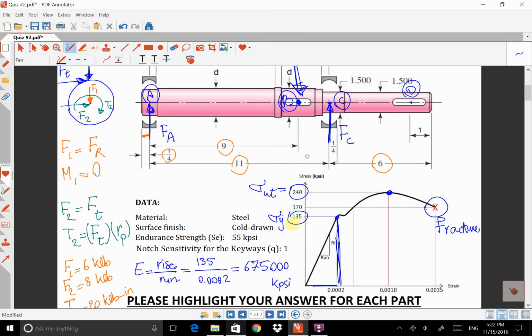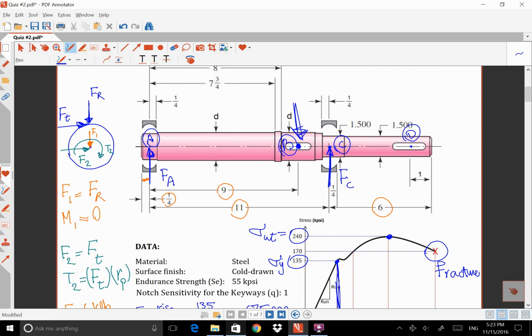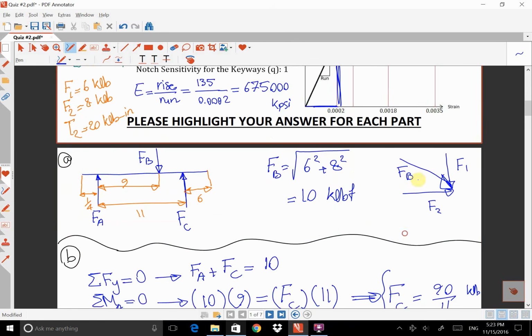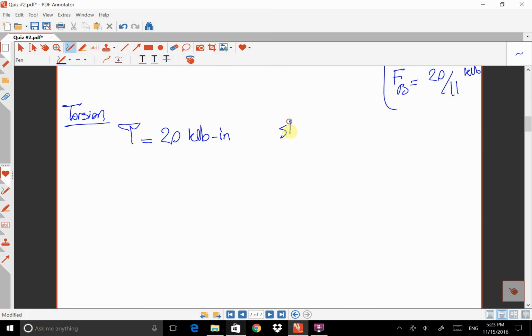If I come to the question, usually torsion comes to a system at one keyway and goes out from the other one. So in this question, that torque applies at point B, and it's going to go out of the system at point D. So we don't have any torsion before point B and after point D. So I'm going to note that one here. I'm going to say there's a steady torque from point B to point D.